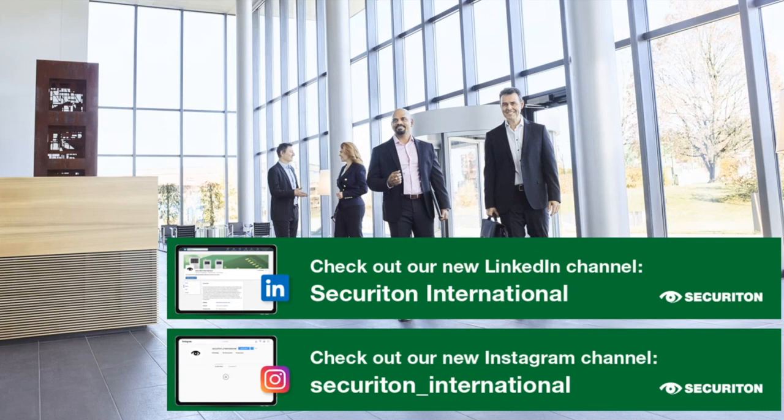The mean time between failure from Securiton is more than 20 years. But even to prove that, our first generation ADW, which is installed in India, has worked more than 20 years without any major issues. So we would say 10 to 20 years without any major issues in terms of the lifetime of the ADW. If frequent maintenance is carried out, you can sustain the ADW for a longer period of time in terms of functionality.